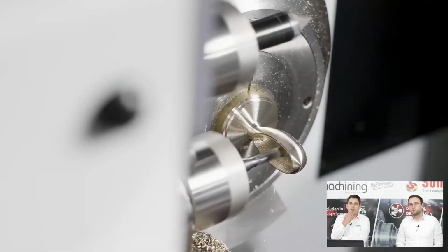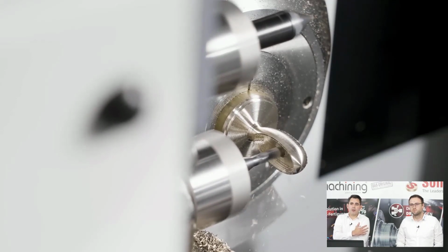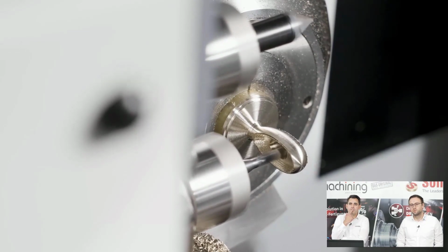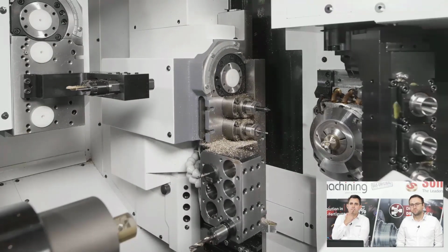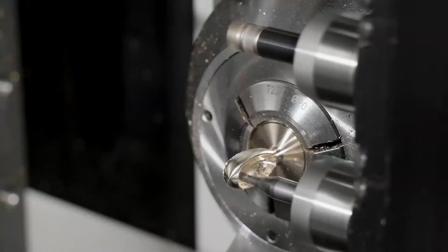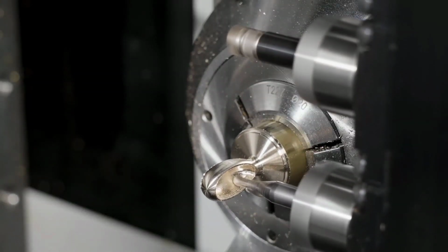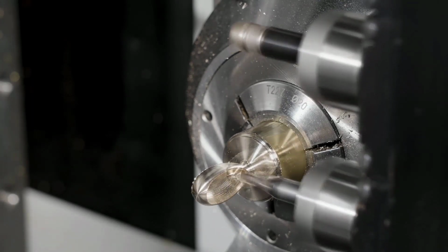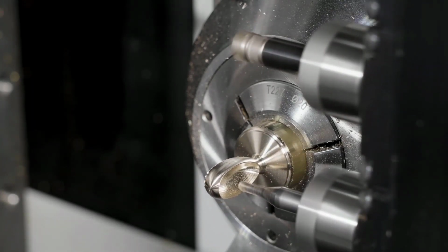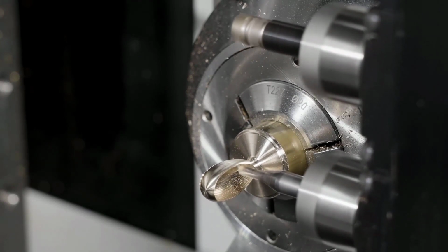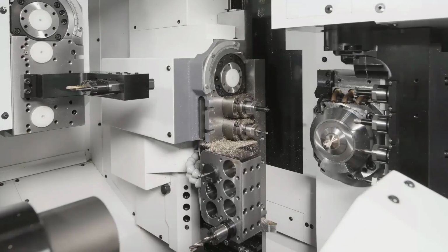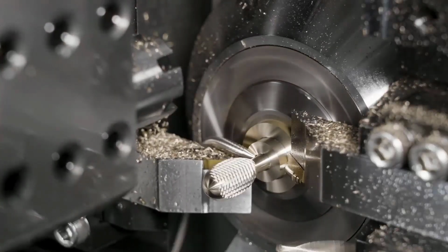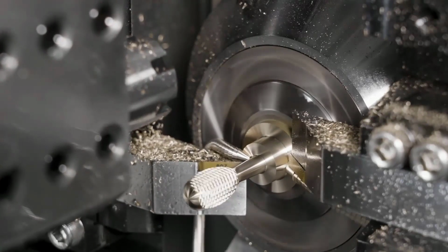Okay, this is now cross machining from the gang tool post number 2. So now the B-axis for the finishing, right? I think this is the tool for the finishing now, the ball nose milling tool. And after that we should see the engraving, or no, it's the simultaneous turning with two different cutting conditions, let's say.